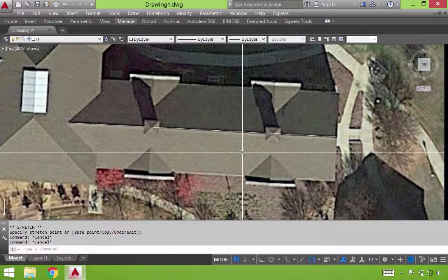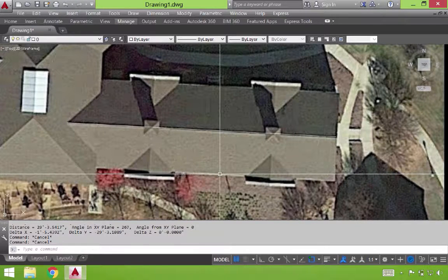When you're creating buildings, it's good practice to use consistent and whole numbers in your offsets. For that reason, the first thing we're going to do is actually determine the distance that we want to offset this line. And it's roughly 30 feet. We'll use our offset command, just O space, type in 30 feet, and offset that line in either direction.